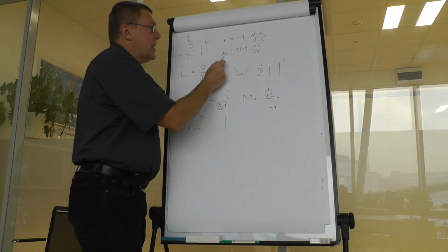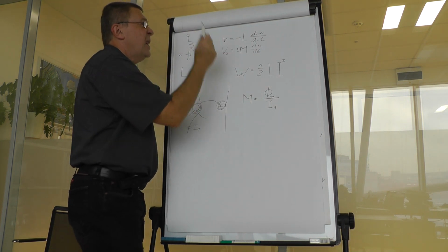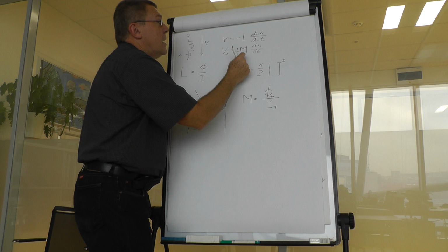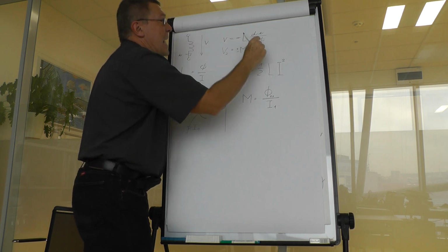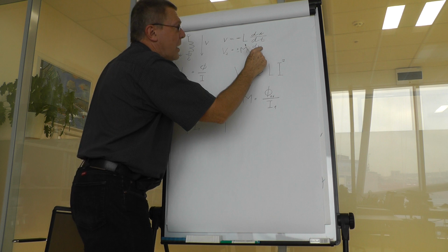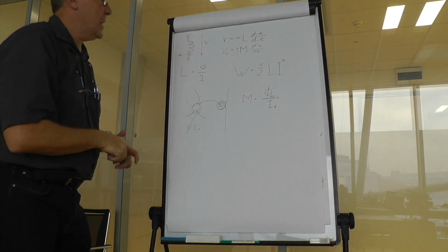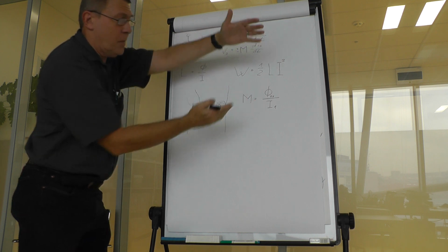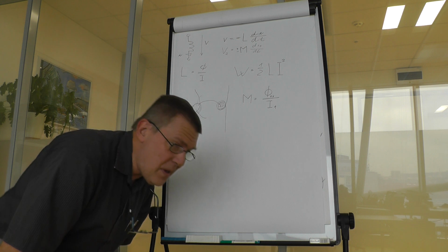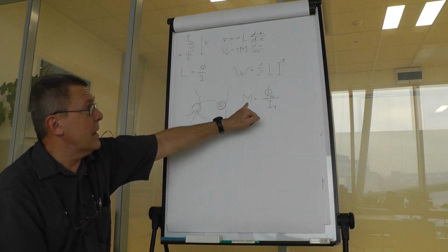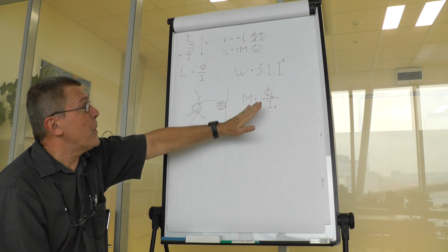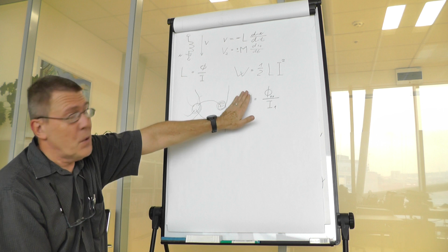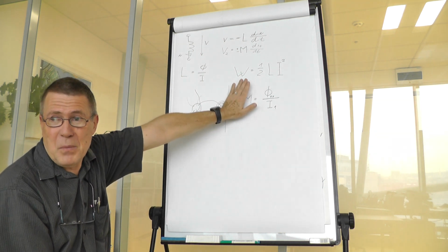So the voltage in the second conductor, voltage 2, is proportional to mutual inductance and time derivative of current in the first conductor. This is again a kind of definition of the same quantity, mutual inductance, based on different physical quantities, but the mutual inductance is still the same in both cases.